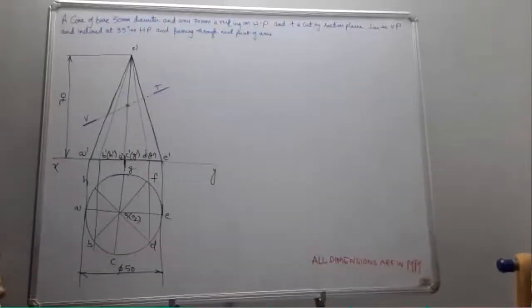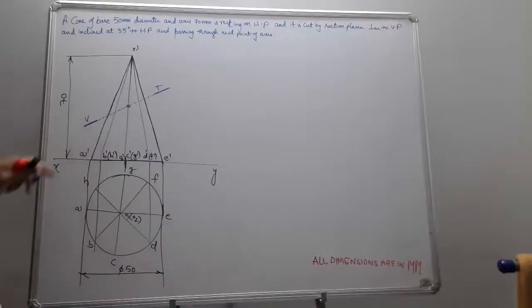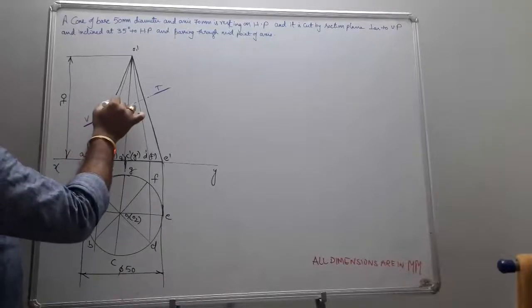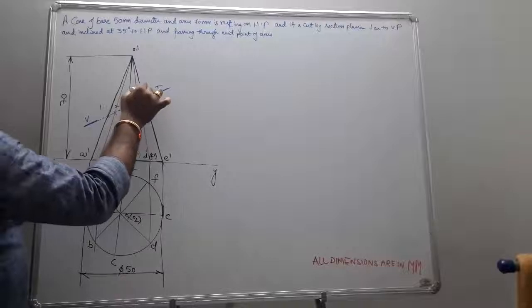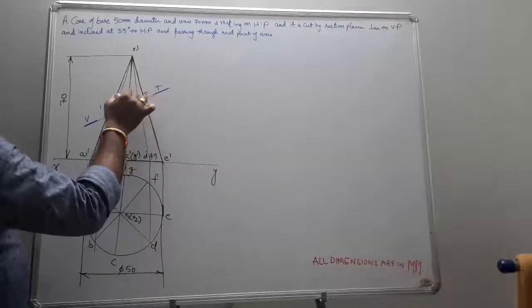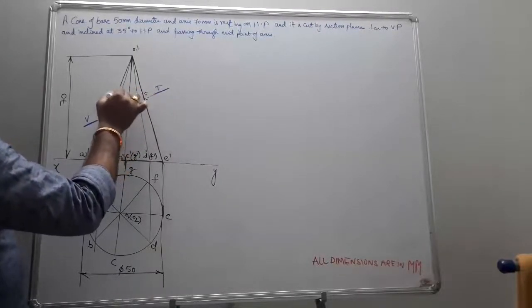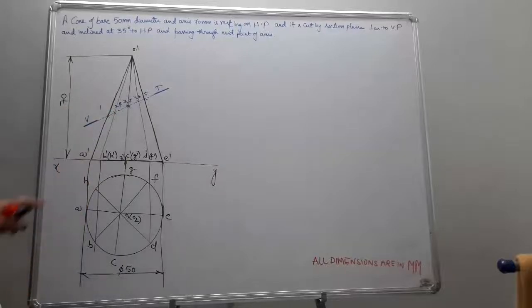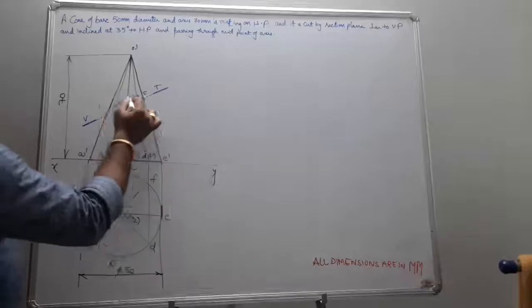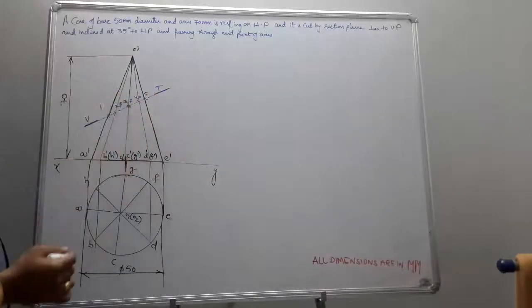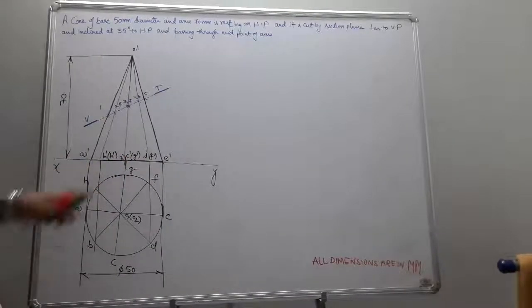Now mark the intersection points. Always start from the extreme left. So this was my 1, 2, 3, 4, 5, 6, 7, 8. Why? Because for all the generators I am supposed to give the numbering 1, 2, 3, 4, 5, and 6, 7, 8 are for F, G, H, which are hidden edges. So 6, 7, 8 points are going to be for those.